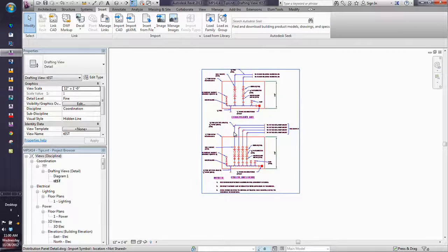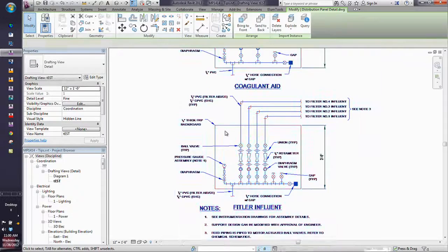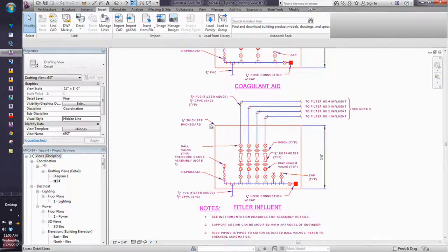All right, so I've got dimensions, and I also have leaders in here that are on specific layers, and they should automatically adapt to what's going on in the model. So if I explode this guy and do a full explode to bring the line work in, you see how the leaders actually change from blue to red? Because I had a line style that matched the layer name, it's just like in old AutoCAD days.